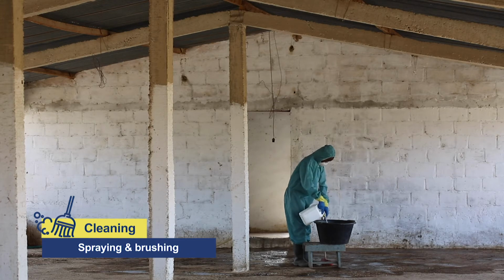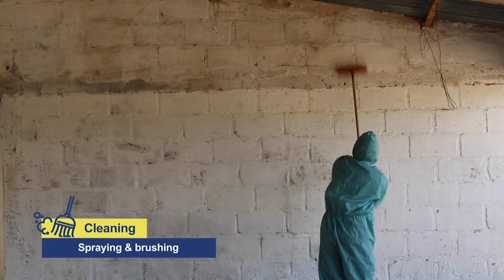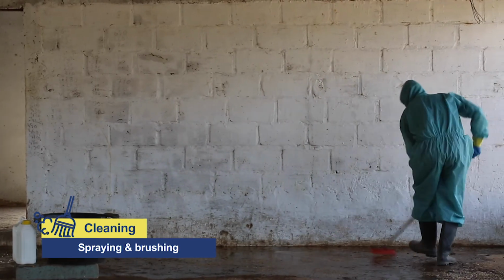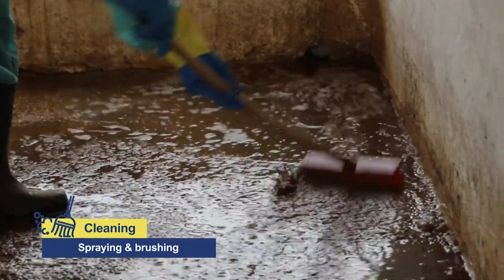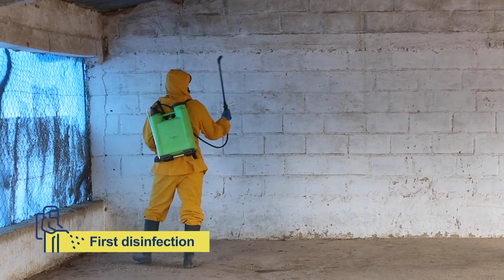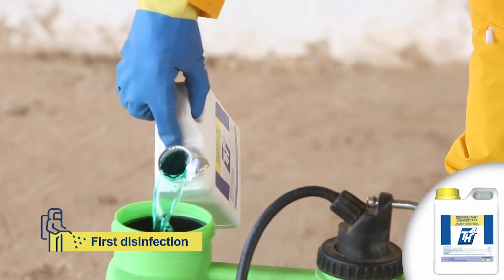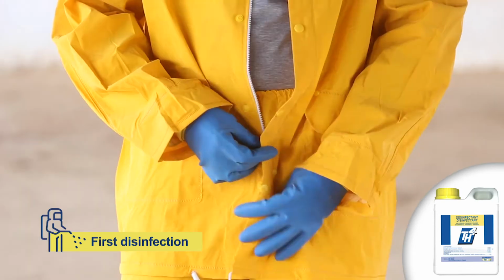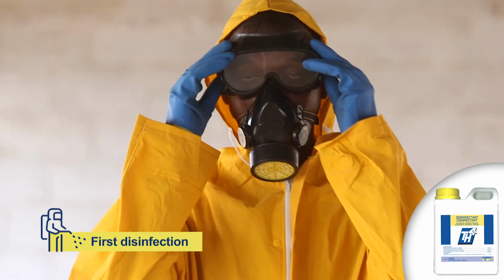30 minutes later, wash the ceiling, walls, and floor with a broom, a stiff brush, and a mixture of drinking water and detergent starting from the top. After rubbing the surfaces, rinse thoroughly and drain the washing water out of the building. On the same day or the next day, close all openings in the building and spray the surfaces with TH4+ using the appropriate equipment for handling this product: protection overalls, gloves, and safety glasses.